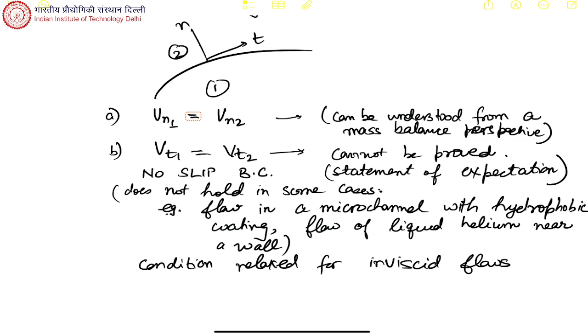If you look at the Navier Stokes equation and the viscous term, then the viscous term has the second derivative. So if you are assuming viscosity is zero, that means you will need one lesser boundary condition, because now the second order term is not being considered in the equation. Therefore, the relaxation of this boundary condition goes well with the mathematics of the problem.